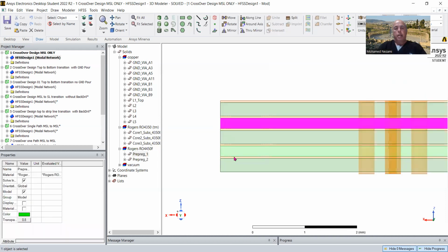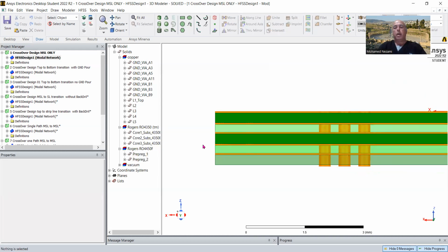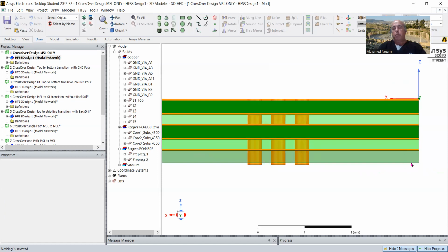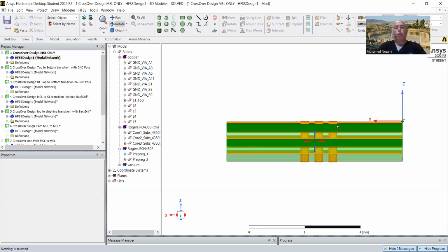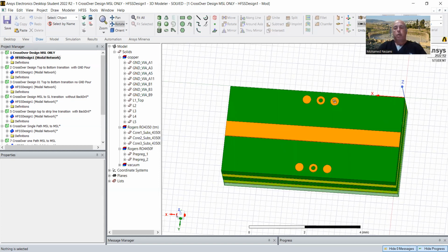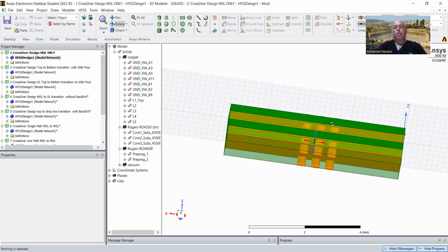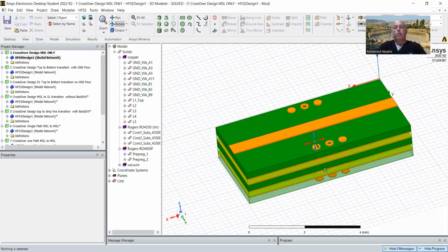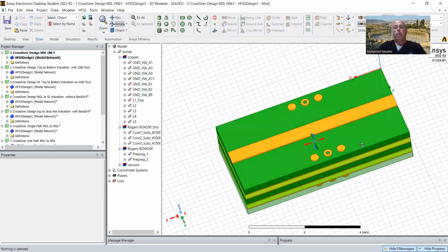This is a pre-preg layer, and this is a pre-preg layer, okay? And then in the middle, at the bottom, you have 1, 2, 3, 4, 5, 6. So that's a 6-layer board, okay? And I threw in 3 vias on each side, put those in place for use later, okay?